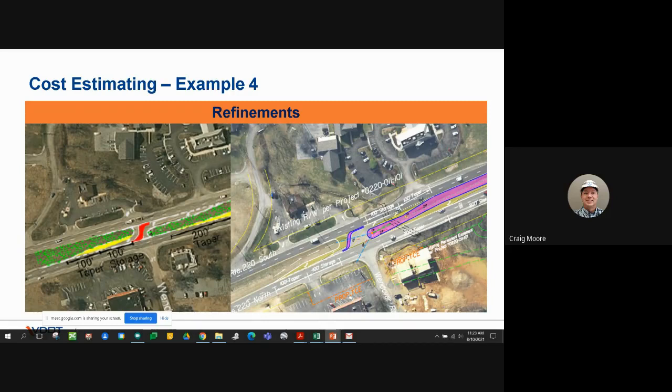On the far right side, I don't have any storm drainage, but I am showing a proposed temporary construction easement on this side. When you look at this, why would that be? Well, again, what are we trying to do to make this U-turn movement? Do we want buses turning through there? Do we want tractor trailers, fire trucks? What are we anticipating, or should we be anticipating and designing for, using this median crossover?